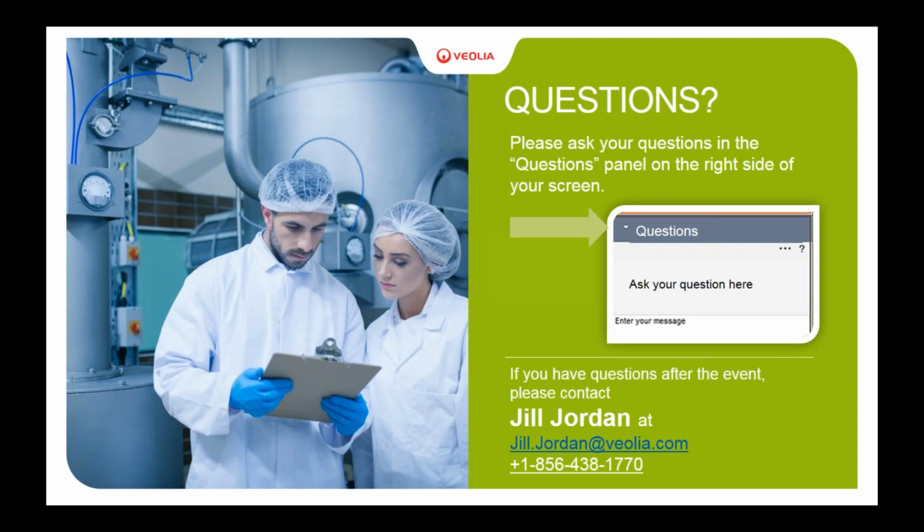But when we classify our systems, currently we do classify the area on the roofs of the reactors as Class 1 Division 1 explosion-proof. So not only explosion-proof light should you have up there, you also need explosion-proof wiring and conduit. That's the key. It's no sense having explosion-proof light if you're going to run regular wiring to it. So that is something that you should have your electrician make sure he does both of that.